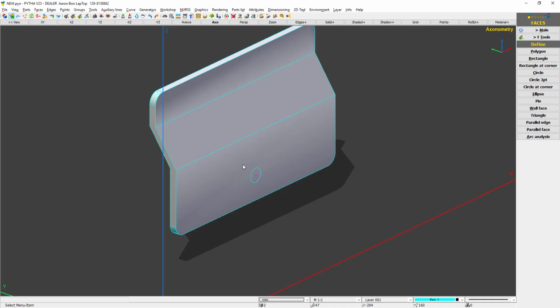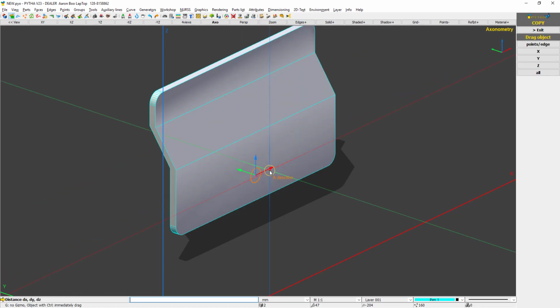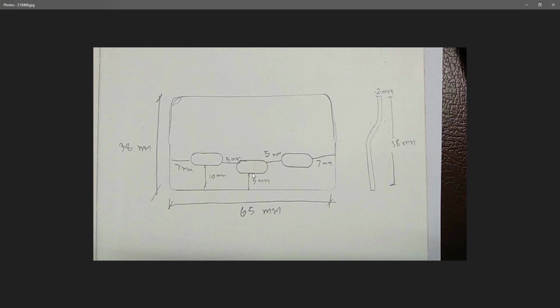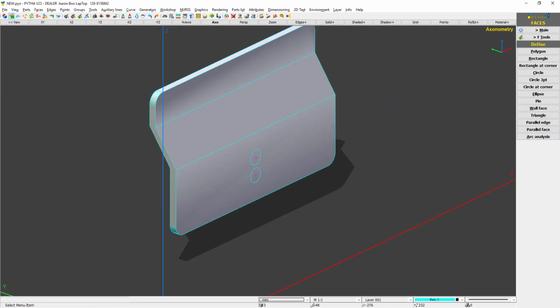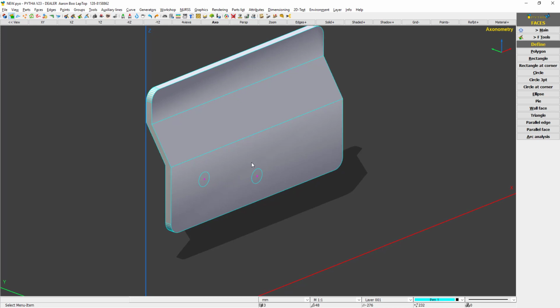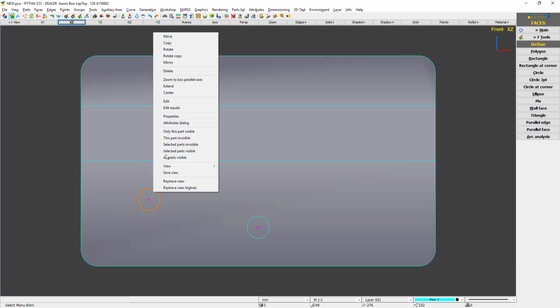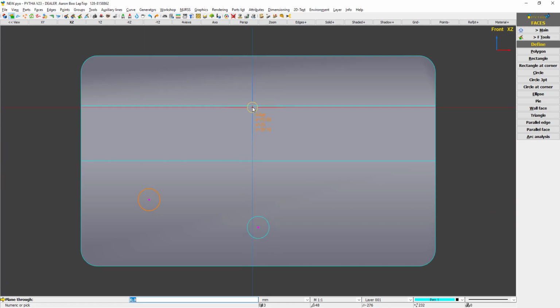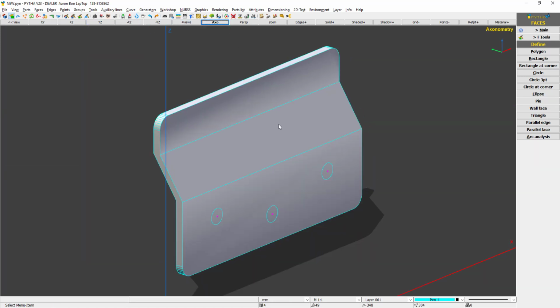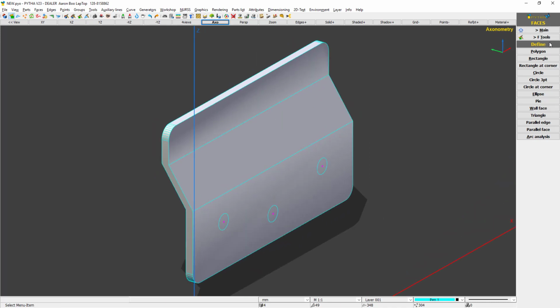Next is somewhere here, another one is somewhere here. Of course we can copy, and I know that it goes up by about 5 mm. Then I'm just going to say move this over here, maybe 20. And if I want to copy this, we can simply say mirror. So I say right click mirror, click on ruler, go to edge center, click. When you do mirror, I recommend that you use it on the 2D view. For beginners, it's very difficult to do mirroring in 3D.